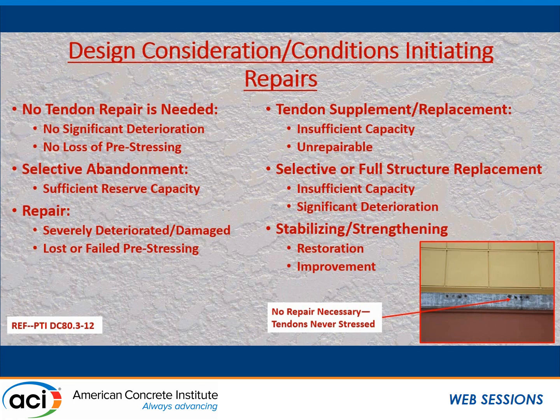and what had happened was these cables had never been stressed. For whatever reason, in this whole slab edge, these 3 cables hadn't been stressed. They grouted over them. And 10 years later, after the slab continued to shorten, the cables were the same length, and it popped the grout caps out. So there was still plenty of tail there. We could grab onto it. It was no big deal.